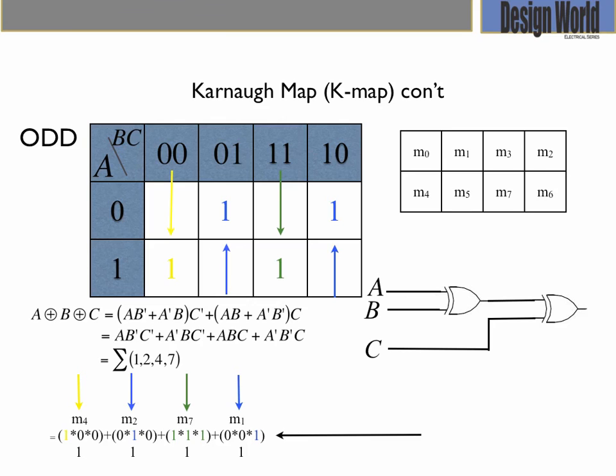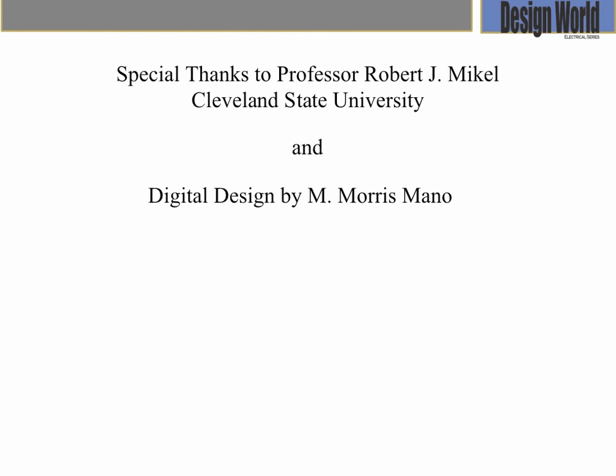The three-input odd function is implemented by means of two-input exclusive OR gates. This concludes Part 2 of the Digital System series. These basics are the foundations to digital logic and Boolean arithmetic and mathematics.